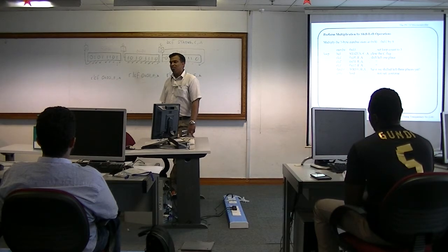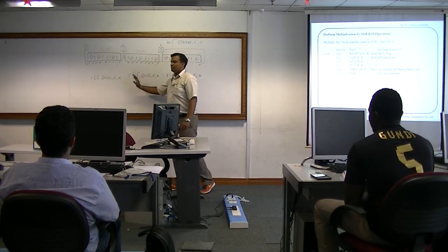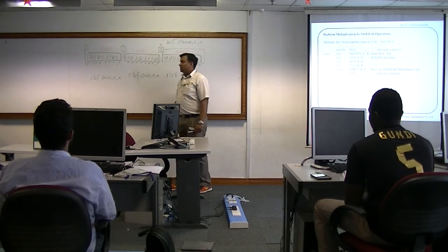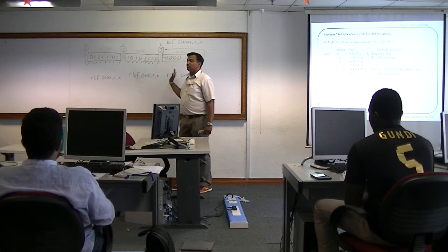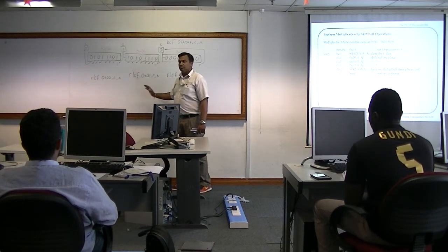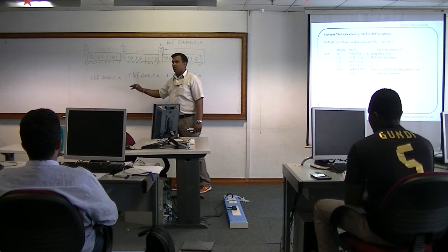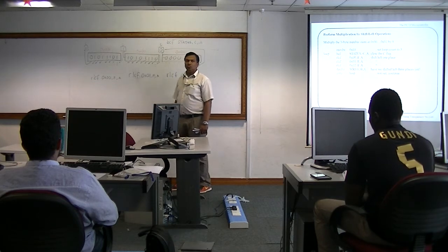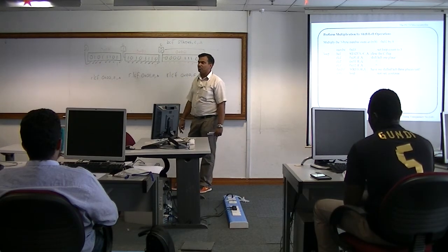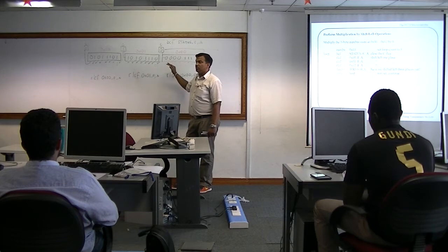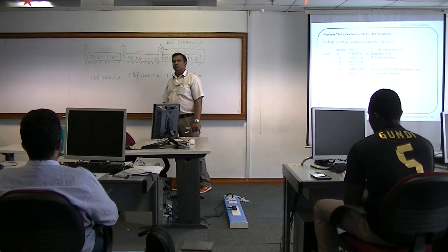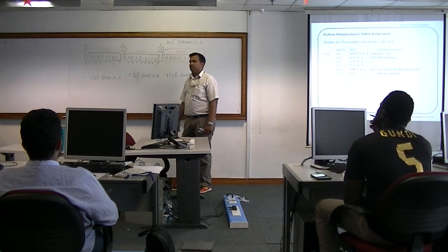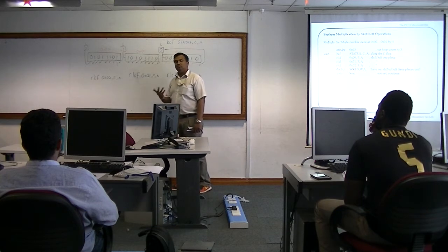Just multiply by 2 only. Don't get fooled: 3 doesn't mean you multiply 3 times. These are just 3 instructions for 3 bytes. So one time you run these 3, you are only multiplying by 2. So you need to rotate this whole instruction how many times? To multiply by 8 means you need to rotate this 3 times.